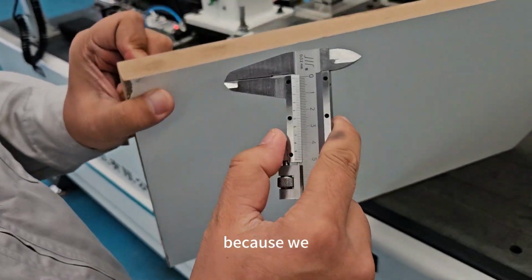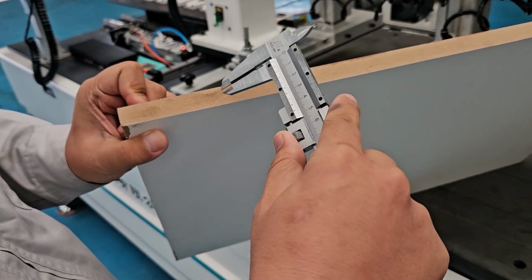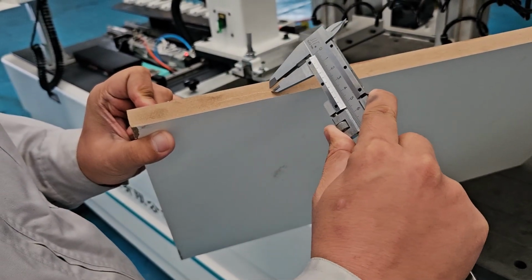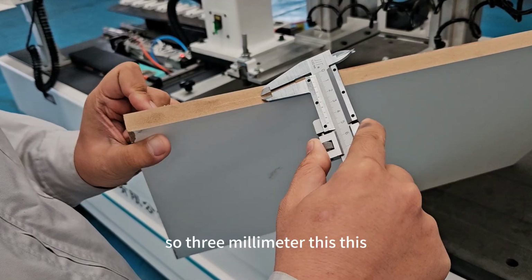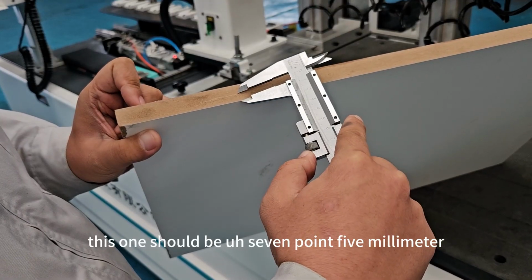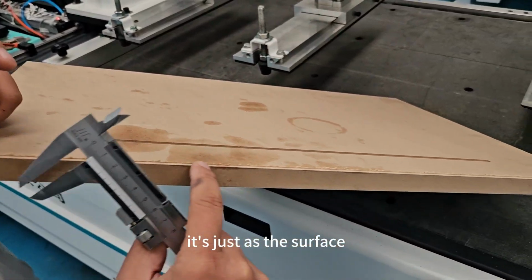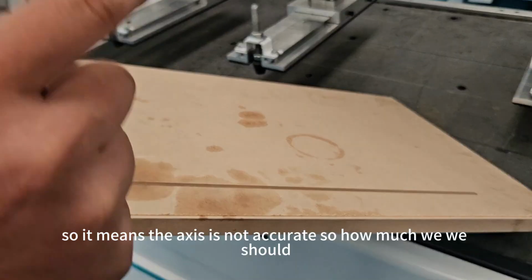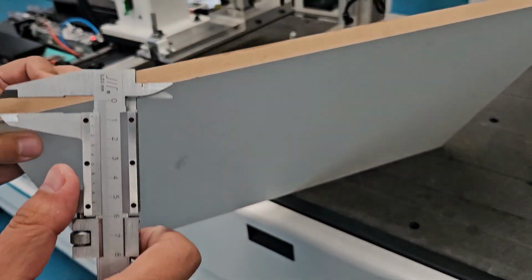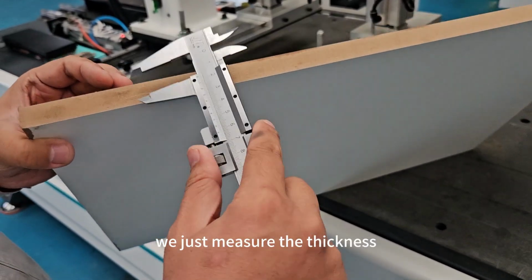Now because we designed the 3 millimeter slot in the middle, it should be in the middle. So 3 millimeter, this one should be 7.5 millimeter. But now you can see it's just at the surface. So it means the axis is not accurate. So how much should we offset?